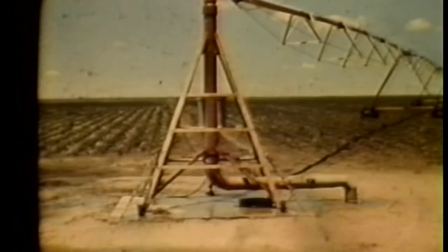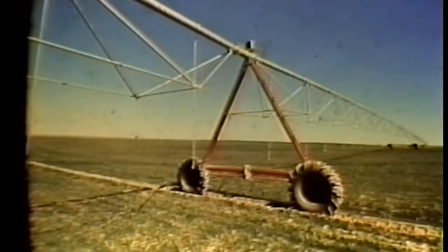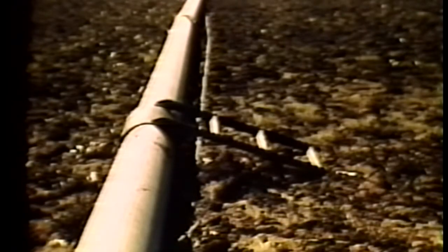The lateral is anchored at one end in the center of the field to a swivel joint that is called the center pivot. The lateral is supported by an under-truss system and towers that are made mobile by wheels. Water is supplied at the center pivot from a well located at the center of the field, or from a mainline supply. If the main line is above ground, provision must be made for each tower of the system to cross over the mainline pipe.